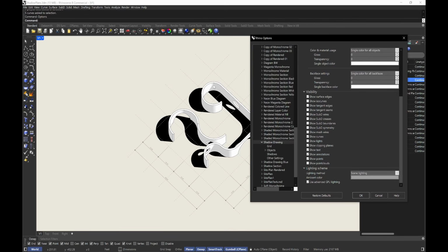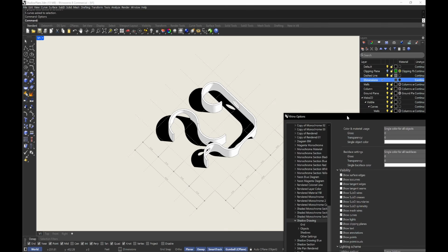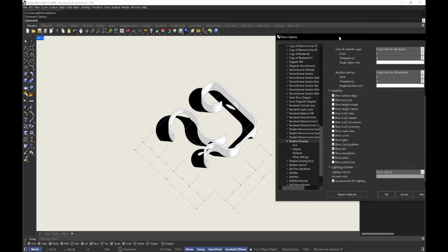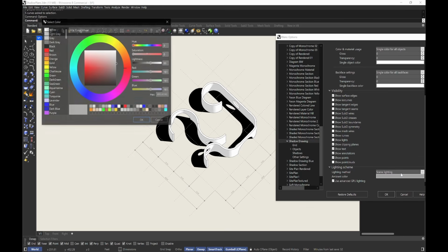Do you see how you start to get a little bit of this interior shadow, but it doesn't become stark black and white anymore? It's just impossible, because you need to see a contrast, so you're going to get a little bit of lightness happening there. So if you do want a little bit of interior shadow in your axonometric diagrams, then you're going to want to show it like that. You need to decrease the ambient lightness.